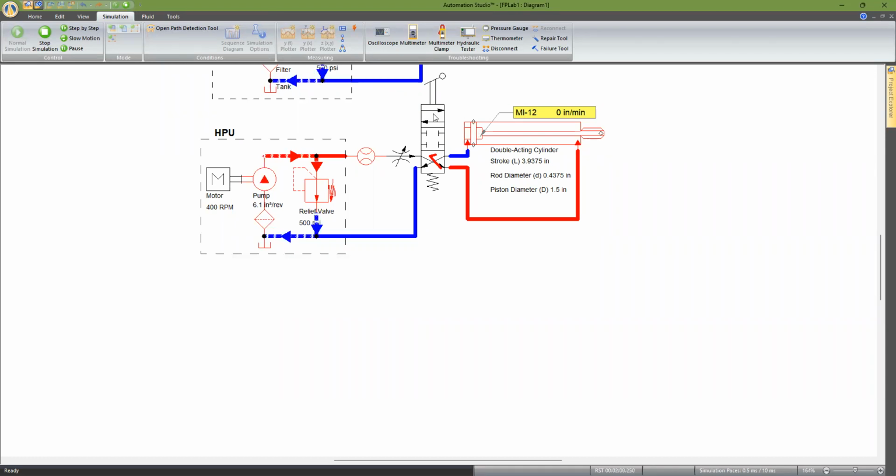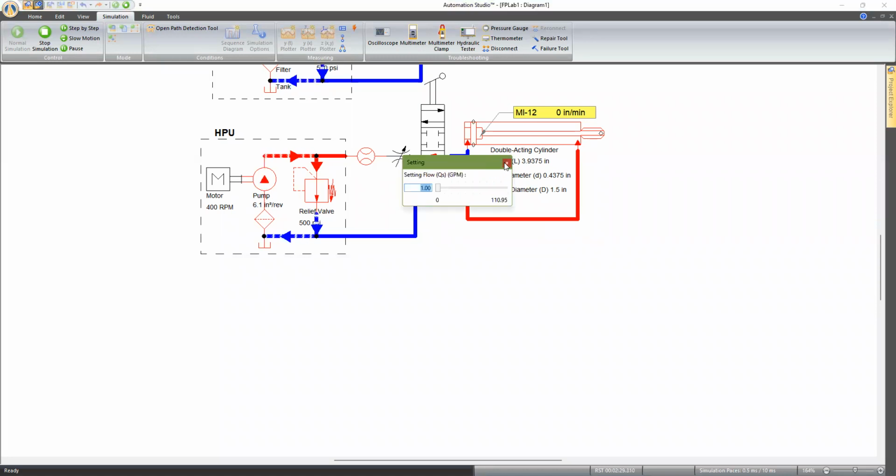So when the piston is extending, you want to read the value corresponding to when the piston was nearing this part. Okay, so it's 129. Although it begins with 140 something, you can always pick the value at the end. Also, for the retraction, don't take the value as soon as it starts. Rather take the value towards the end of the stroke, like 141. So retraction speed is clearly 141 when you have a flow rate of 1 GPM.